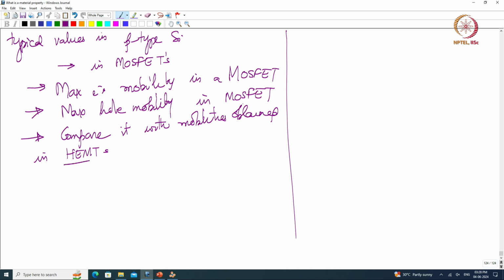As a result, since the electrons actually travel much faster, you can use these HEMTs for what is called gigahertz electronics, which means that the mobility of electrons should be such that if I have gigahertz pulses, the electrons should actually respond to these pulses. They cannot move slower than gigahertz. Whereas in normal transistors that may not be the case; that is indeed not the case in silicon transistors. So if you want gigahertz electronics, you may want to use HEMTs. That is the basic idea of what HEMTs are, and this is not a transistor course, so I am not going into details of this.